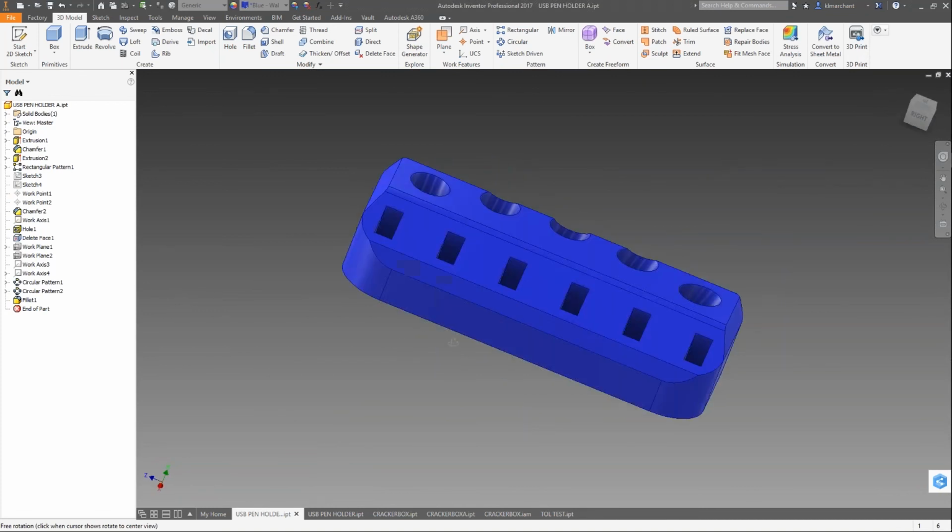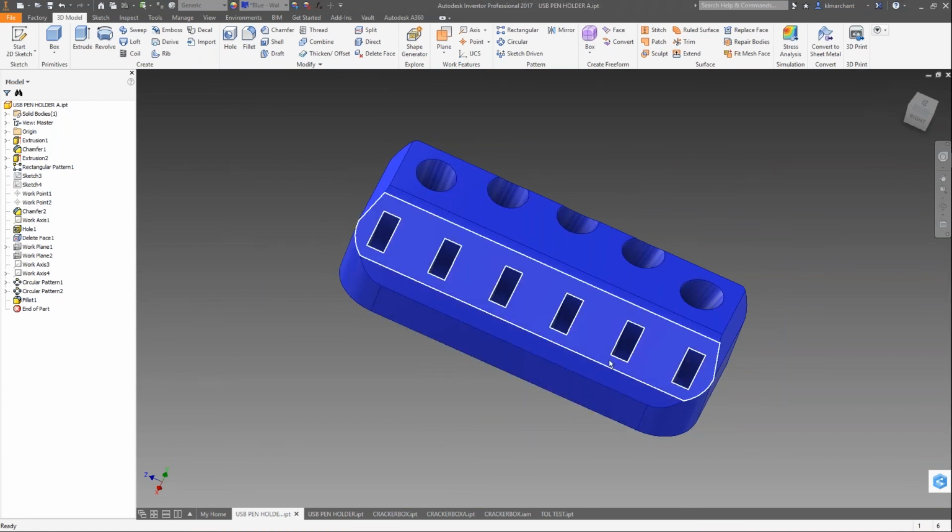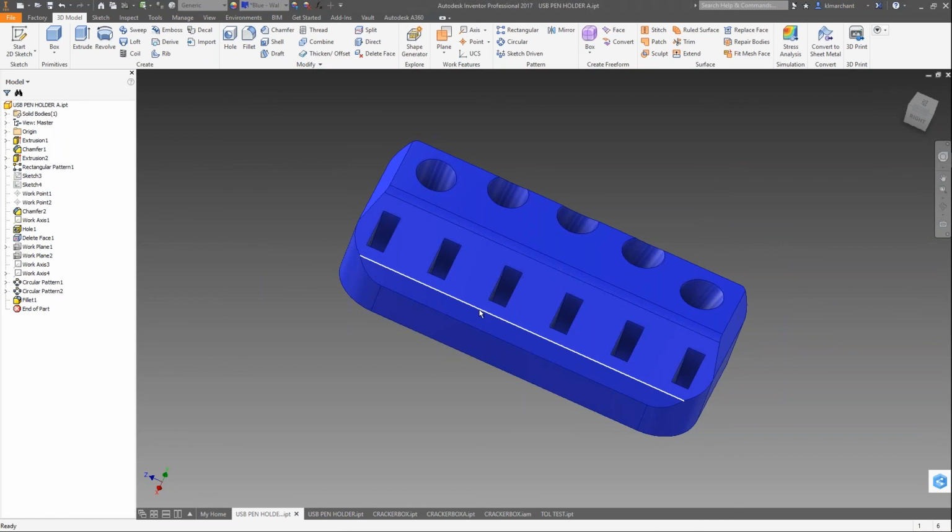If I've got a large diameter, I may not even see that 0.02 thickness, versus if I'm running a smaller head that's going to take longer to print but give me a higher resolution, I may even be able to see all the way down to that 0.01 and see the lack of material there.